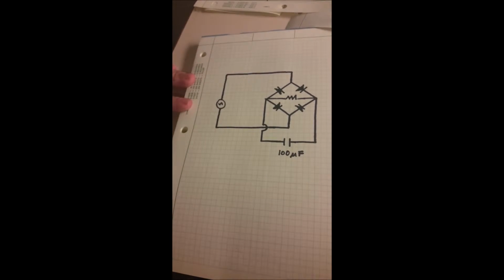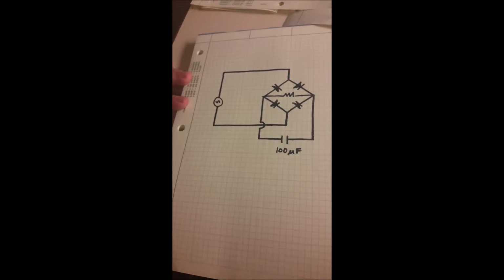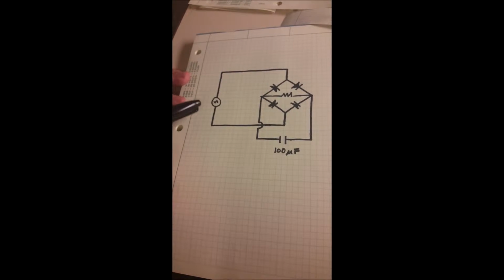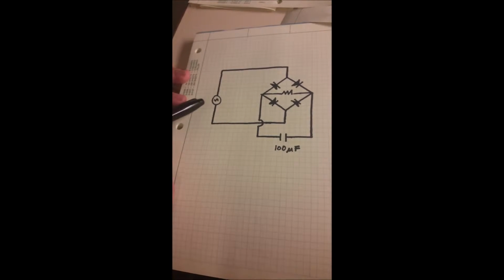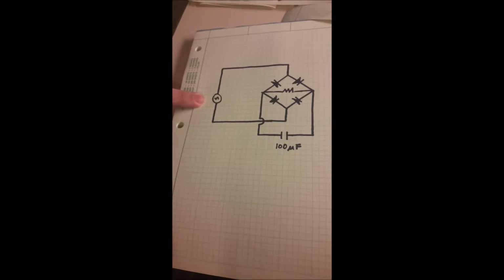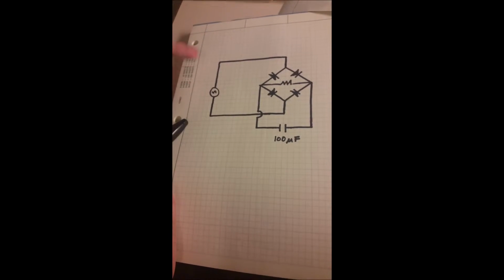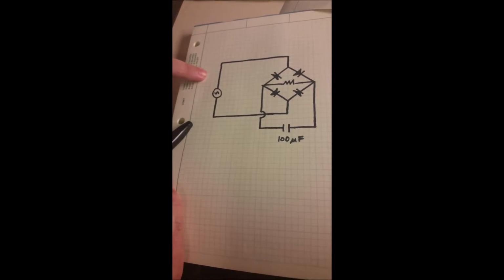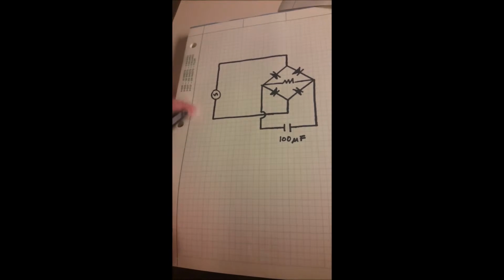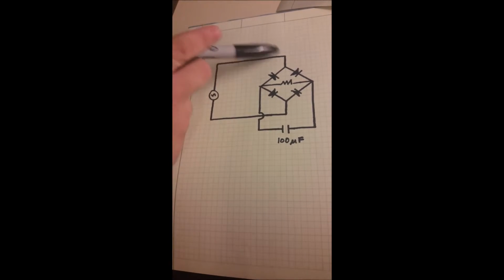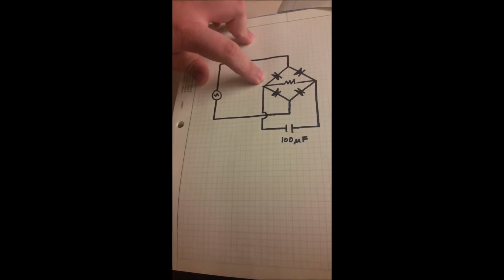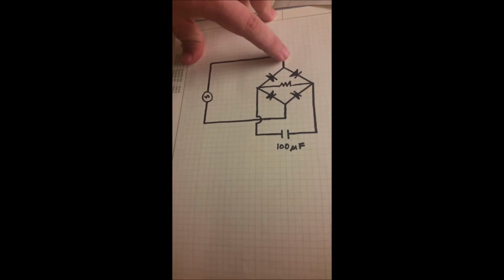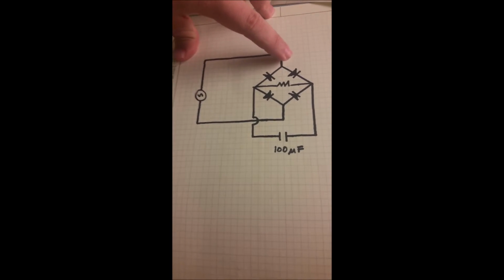This is going to be a basic schematic of a rectifier that we talked about previously. This here would be an alternating current source. Notice the squiggly line in the center of the circle. So as time passes, the direction of flow out of this is going to alternate between positive being on top and positive being on bottom. So as the current comes around to being on the top here, these triangles denote the different diodes. Diodes only allow current to flow in the direction that the triangle is facing.